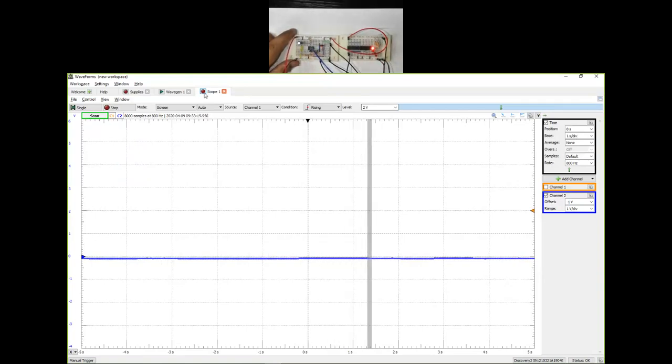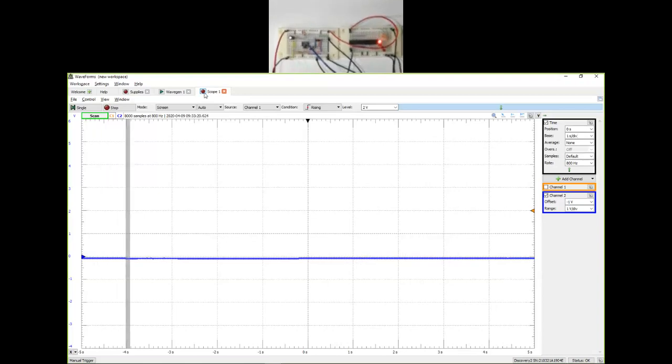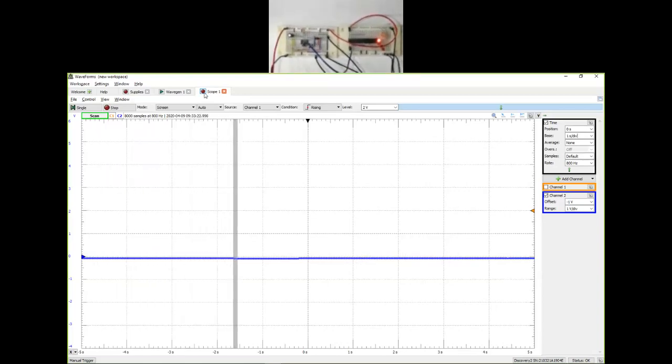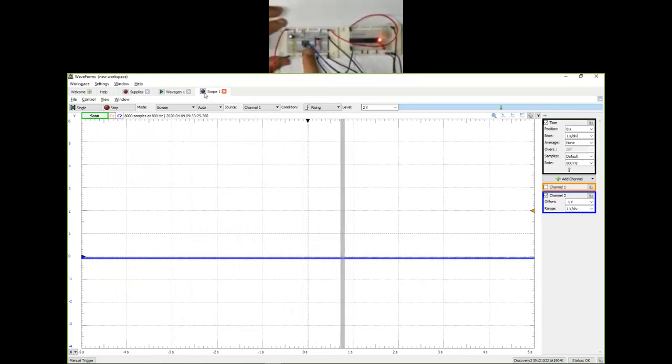I hope you guys are able to see this. The counter initially incremented a couple of times, even though I didn't want that to happen. So that went from 1 to a few. So 7 here, 8 here, 9 there, 10 there, 11, 12 is okay, 13 is okay, 14 is okay, 15 is okay, 0 is okay, 1 is okay, 2 is okay, 3 is okay. So it's doing good on some presses, but it is still bouncing on the other presses.